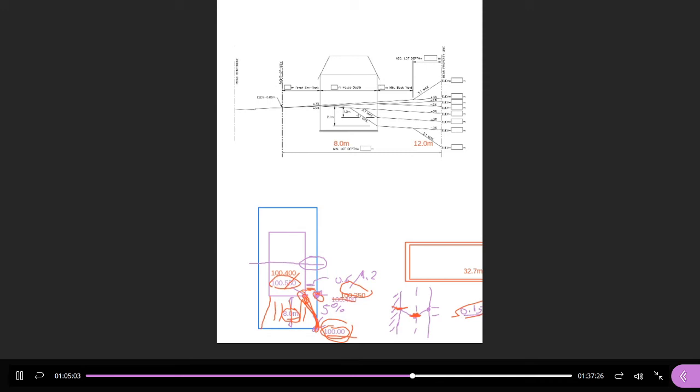Now we're starting to get lower and lower, right? We started way high and we're starting to come further and further down. We're starting to be compatible with the front and the back. So now instead of 3% at the front, we're going to use the minimum 2%. So for the rest of the scenarios, we're going to use 2%. There's a couple of options for the next scenario. Now we get into the split draining lots.